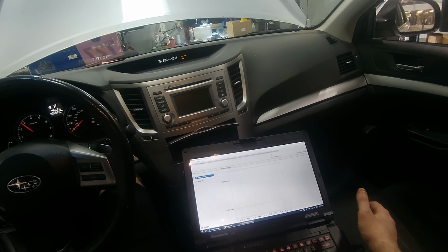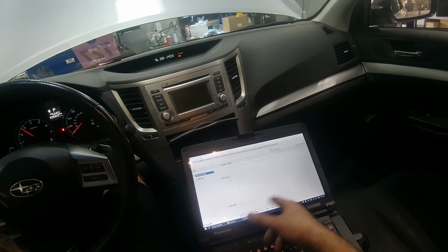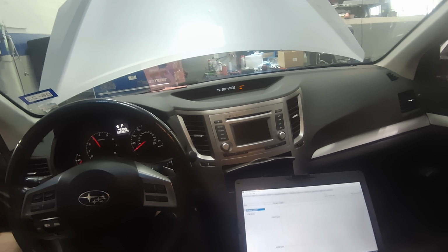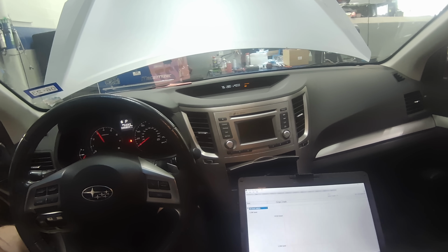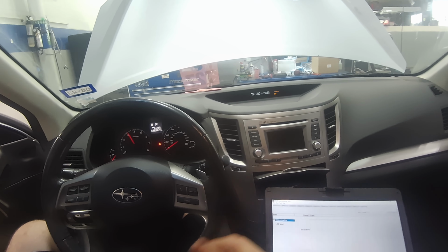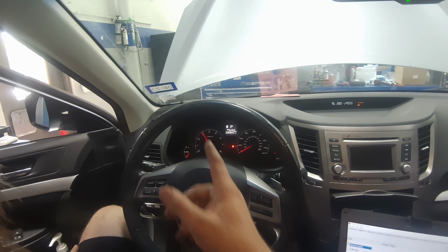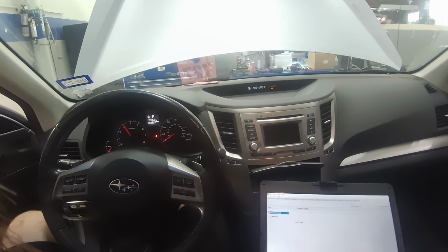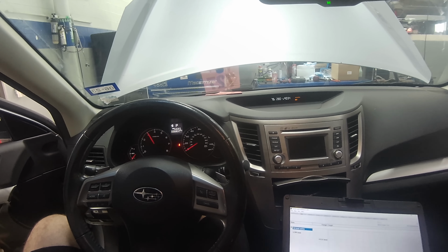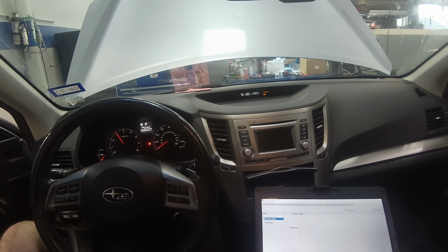So you can see how being half a quart to three-quarters of a quart low can trigger these. But what happens if we keep this up? If we run out of oil, we run out of pressure. It's just like gas in the gas tank. You run out of gas, you can't accelerate anymore. So at low pressure, that light comes on. So don't get these two things confused. What are we going to recommend to the customer? We're going to recommend to fix their oil leak.